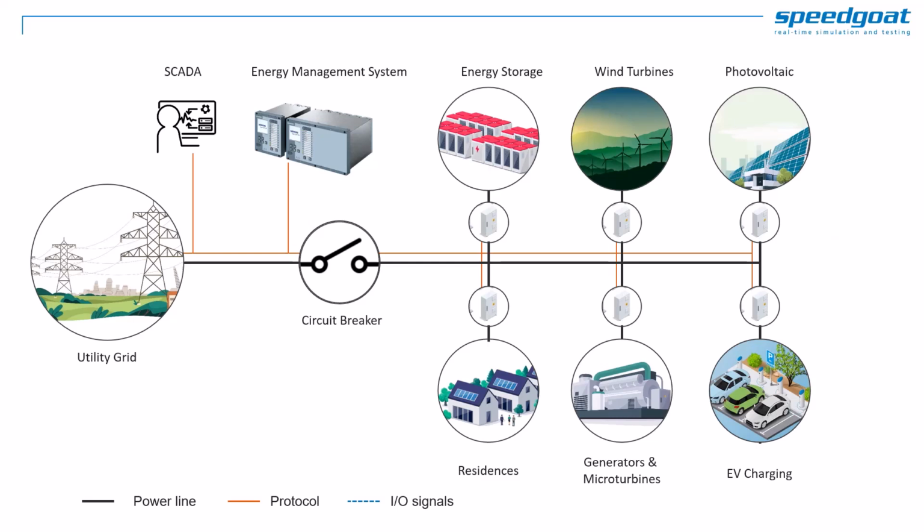An EMS for microgrids is a control platform designed to optimize the generation, storage, and distribution of energy within a localized grid. In addition, the EMS coordinates connection to the utility grid with the potential for islanding operation when disconnected from it. The EMS coordinates different energy sources such as solar, wind, and conventional generators, and energy storage like batteries, in-grid energy storage, or electric vehicles.